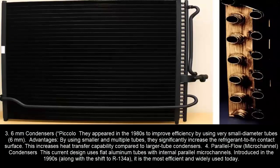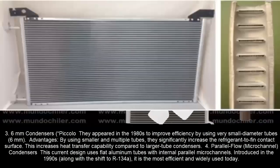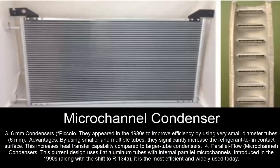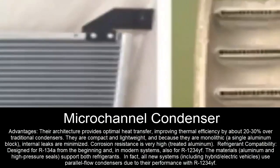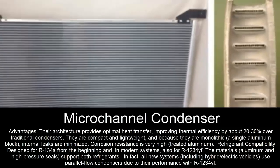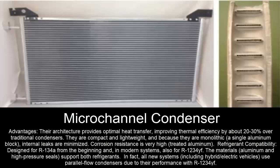4. Parallel flow microchannel condensers. This current design uses flat aluminum tubes with internal parallel microchannels. Introduced in the 1990s, along with the shift to R134A, it is the most efficient and widely used today. Advantages: their architecture provides optimal heat transfer, improving thermal efficiency by about 20 to 30% over traditional condensers. They are compact and lightweight, and because they are monolithic, a single aluminum block, internal leaks are minimized. Corrosion resistance is very high, treated aluminum.